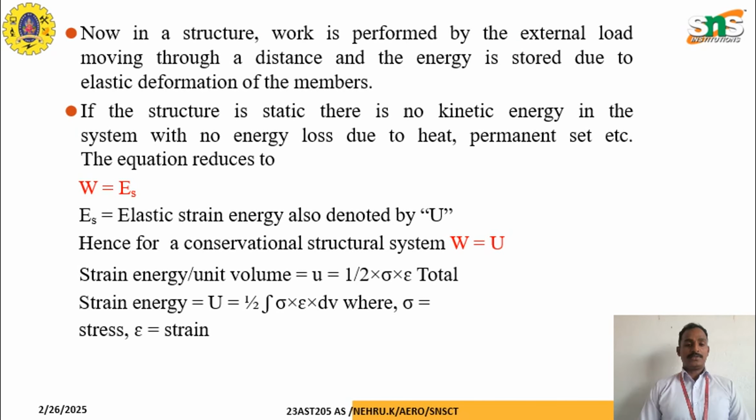Now in structures, work is performed by the external load moving through a distance, and the energy is stored due to the elastic deformation of the member. If the structure is static, there is no kinetic energy, in a system with no energy loss due to heat, permanent set, etc. The equation reduces to W equal to E, that is the elastic strain energy, also denoted by U.